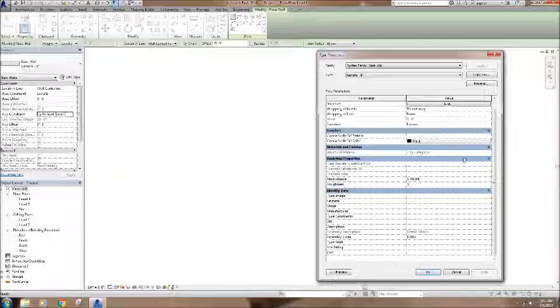Absorbance and roughness, these are more for your building, and if you were building an analytical model, you can set the overall thermal resistance and U factor and all of that sort of stuff for the wall, so that Revit can take that into account when doing the analytics.